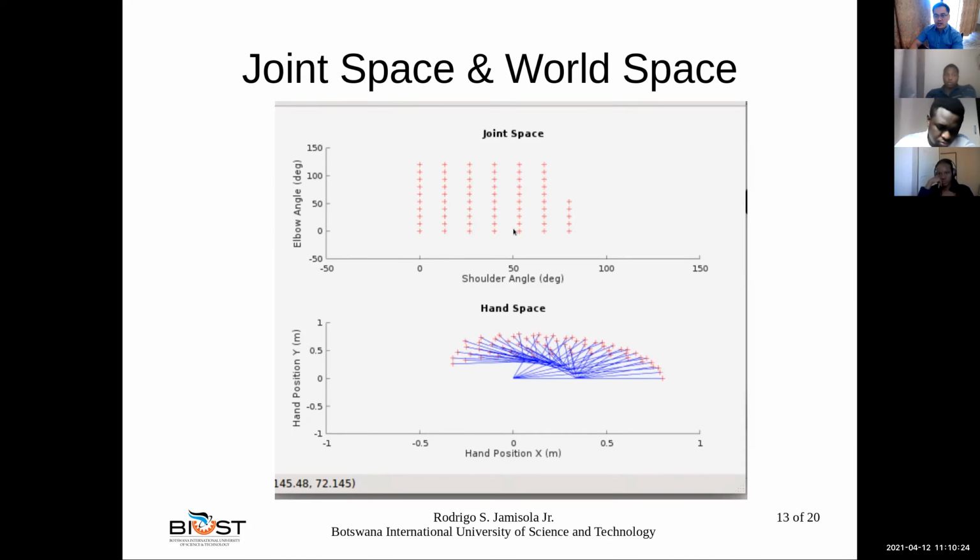So here we say forward because we pick a point in the joint space and then we draw the configuration of the robot, or the arm posture. For example, this point of 0, 0 is the flat robot, with 0 angle of joint 1 and 0 angle of joint 2, just lying down like that. Then we increase joint 2 and it will sweep like a fan. Then increase joint 1 and this part sweeps like a fan, keep on increasing the joint values.